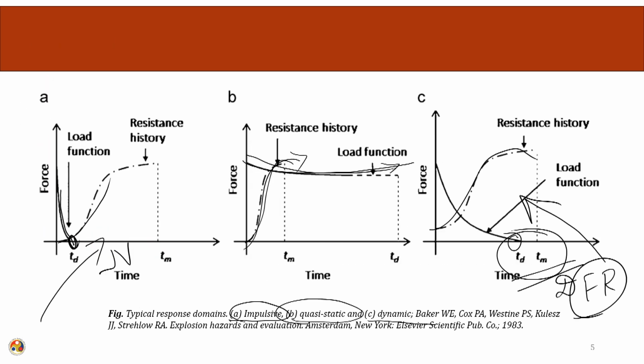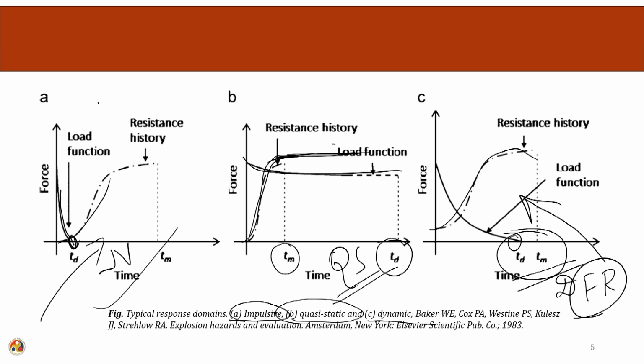Here, if you see, the loading is continuing. The structural response has already started and it has saturated. So, the loading period is more than the structural response. The structural response normally attains its peak well before the loading ends and it reaches an asymptotic level. There is no significant dynamic amplification here. So, this is what we are considering as the quasi static loading. Near field loading for the impulsive part, far field loading for the dynamic part, and quasi static loading here.